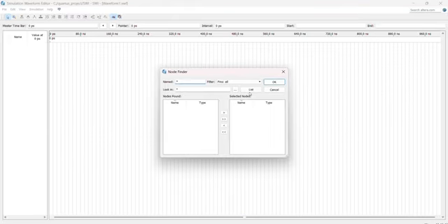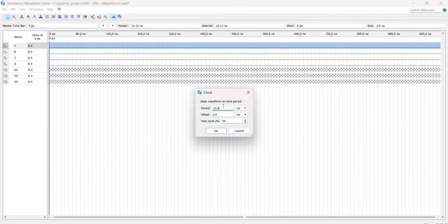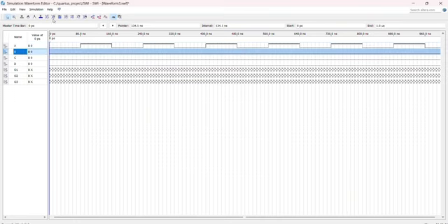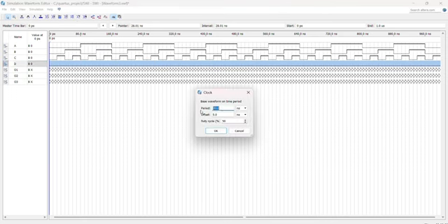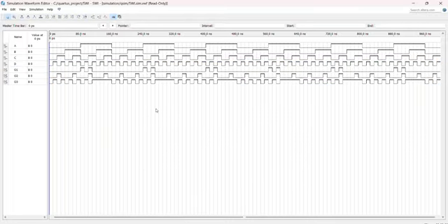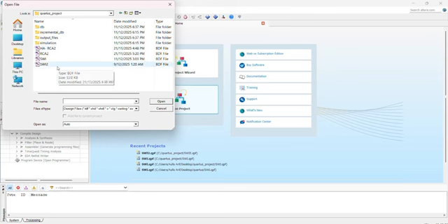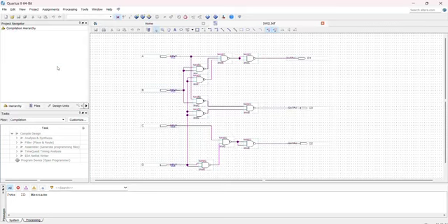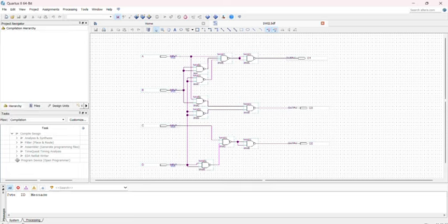First, you need to create your logic circuit, as we have done earlier. After you've done that, we need to set up the simulation. After our circuit is compiled, we will need to create a VWF for simulation. So create a new file: go to file, new, select verification, debugging files, and then choose your file name, and then set end time. In the VWF window, set the desired length of your simulation.